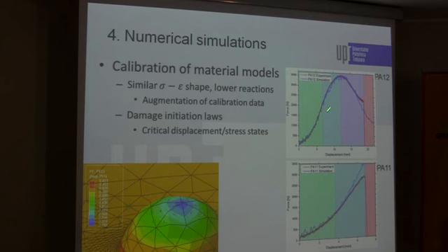So the first one, the green one, seen in both cases, we consider an elastic part. The blue one considers the onset of plastic deformation. In the case of the PA12, we have this purple region, which is a combination of the material slip and the progressive degradation of the material, and the red area, which is the damage onset. And through this, we calculated the critical displacement for each test,